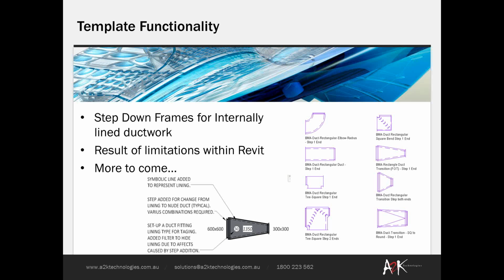Another recent addition to the template has been an example here of these step-down frames for ductwork. So when you're going from lined or insulated ductwork to uninsulated, the way that it is at the moment with the software, the functionality of the installation doesn't allow you to define these stepped-in or recessed frames, which is what you would necessarily be expecting to see.